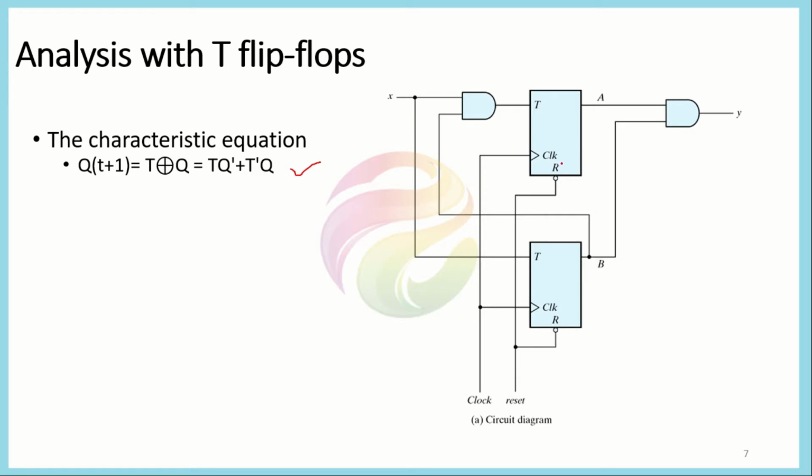Suppose we have a system here that is represented in the form of two flip-flops. It has some combinational part for both the input and the output of the system. For this system, we would be analyzing what the main functionality is, or how this system is performing. We would have two states here, one would be A and the other would be B. So overall there would be four circles representing the state diagram. But first we have to represent this whole process in the form of a state transition table.